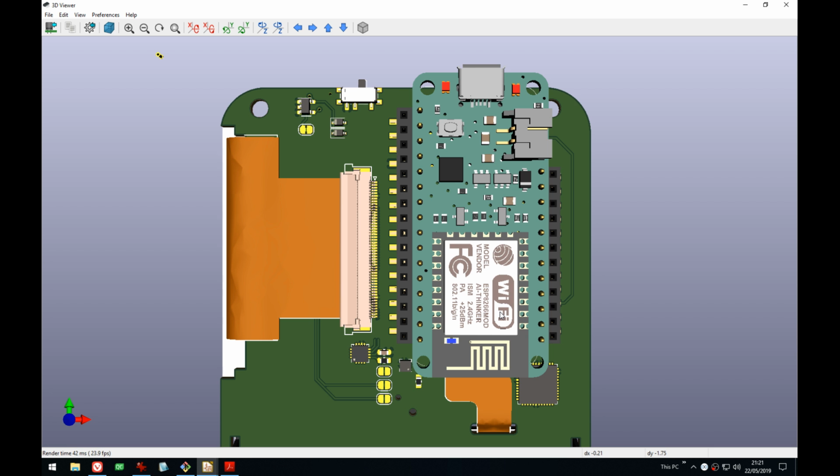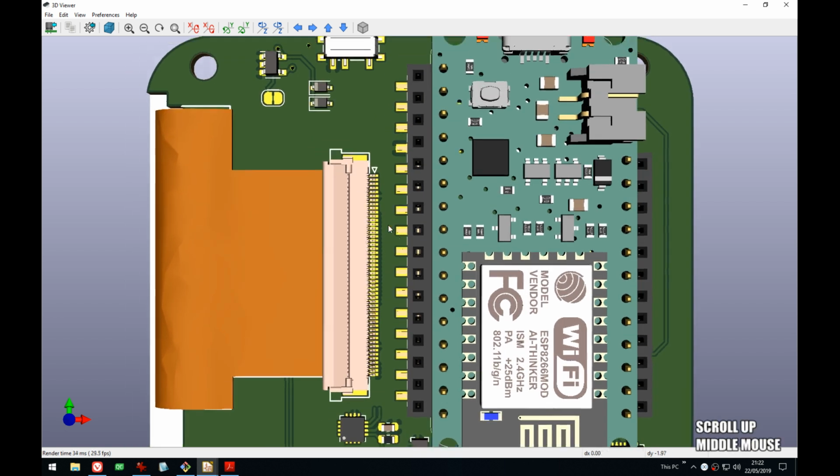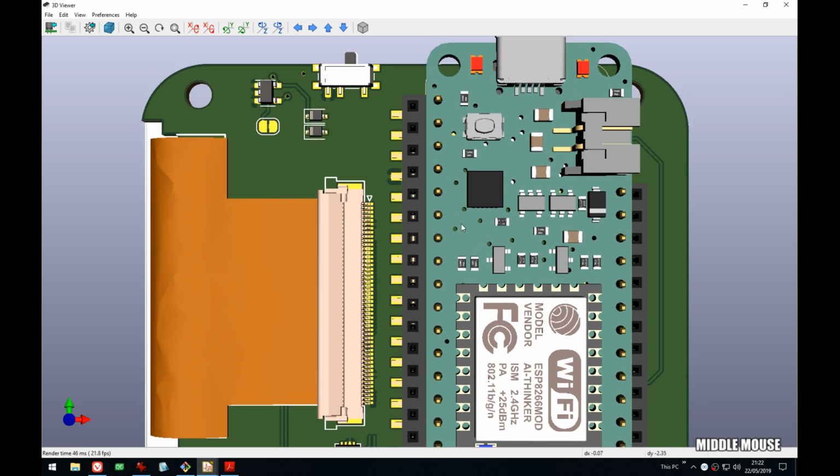And then you might want to look at how many components it needs. Is it just decoupling? Some of them are variable, so they need resistors to set the actual voltage. Battery power, yeah, exactly, that's true. With battery power, you have to make sure that even at the lowest, almost empty battery, you will still have enough to supply the output voltage that you want. And it's kind of like that with everything.